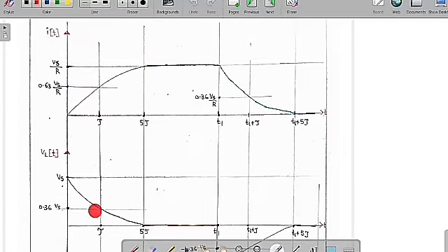Similarly, in the charging mode, the voltage across the inductor is going to decay. So now VL(t) is equal to Vs into e to the power of minus t by tau. Because of that, it is going to decay. Within 5 tau, it is going to reach the value of 0. So we can say if this is 63%, this value will now become 36%, so 36% of the final value. At steady state, the current is going to reach the maximum value. If the current is maximum, then di/dt is 0, so the voltage will be 0 across the inductor.